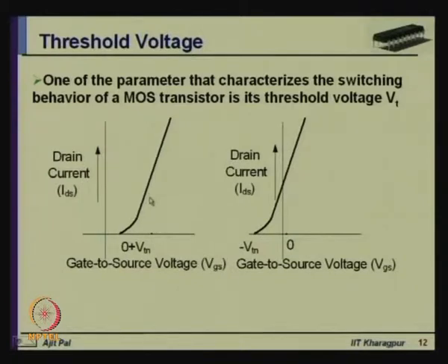So, it increases at this rate. So far as the depletion type transistor is concerned, the curve is somewhat similar, but it will be shifted towards the negative quadrant. As you can see, you have to apply a minus VTN, a threshold voltage, to stop the flow of current. And if you increase from negative to less negative to 0 and then positive, then the drain current increases following the same nature of curve, and of course, the amount of current will be dependent on the gate voltage.